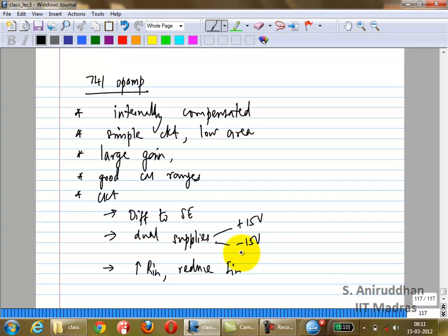The way you're going to do it is very similar to the case of the MOSFET. You can see at least half the concerns are very similar. Differential to single-ended: you want some gain from the first stage. Why do you want that? Because if you have noise or offsets in the second and subsequent stages, they'll get divided down by the gain of the first stage. So you want some gain in the early stages, and probably more gain somewhere in the middle. This happens to be a 3-stage op-amp. Because you're going to use it in general purpose, you also want very low output impedance, so you can drive very large loads. Your output impedance needs to be extremely small.